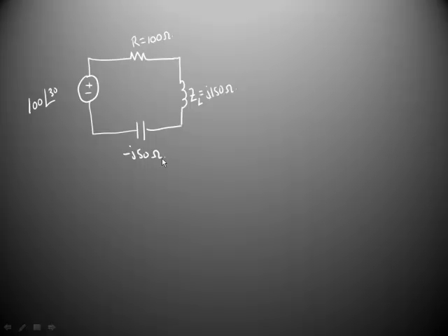If we were looking at this circuit as if it were all purely resistances and voltage sources back in the DC case, and we wanted to find the current flowing through all three circuit elements and the voltages across all three circuit elements, one of the ways we might do it would be to collapse the circuit down until we had a single equivalent impedance, and then take that impedance and divide it into the voltage and come up with a current using Ohm's law. So let's go ahead and try that.